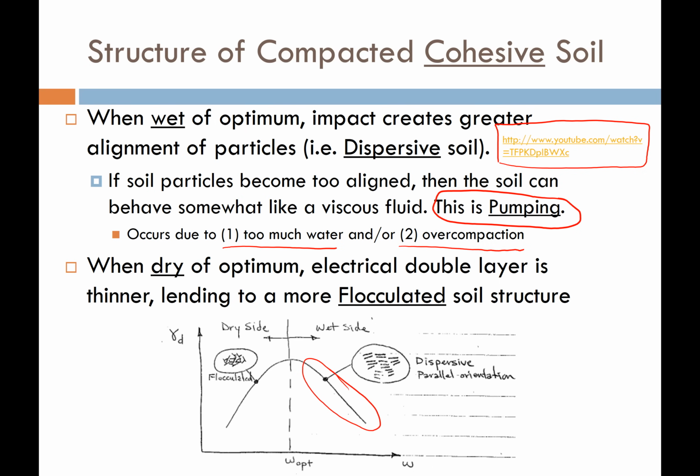It's a great example to show what soil looks like when it gets in this pumping or dispersive condition. And in general, unless we're placing really deep fills, this is kind of an undesirable condition. We'd rather have the soil be dry of optimum, so the soil behaves more in a flocculated manner, because then the soil strength is generally better.